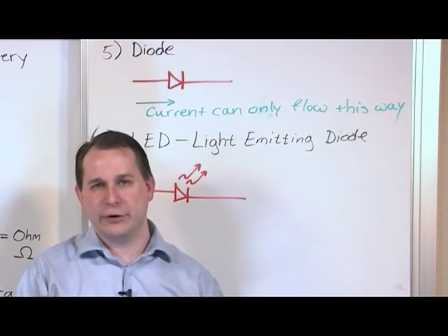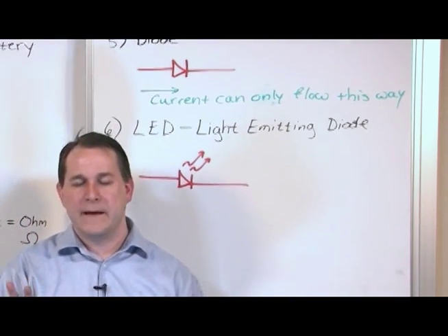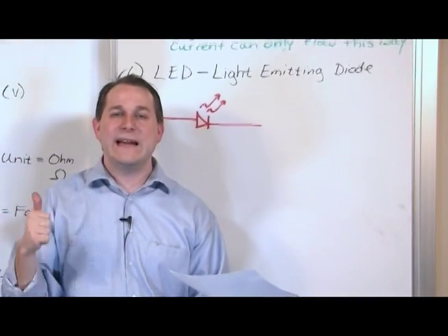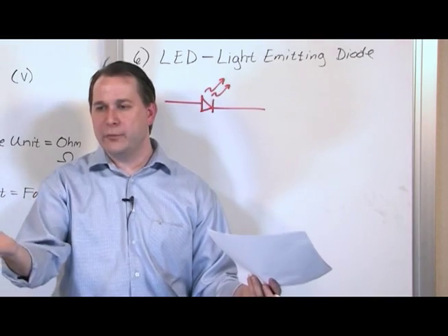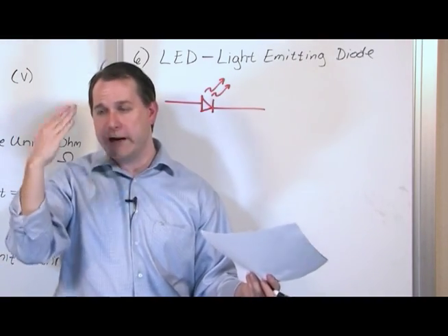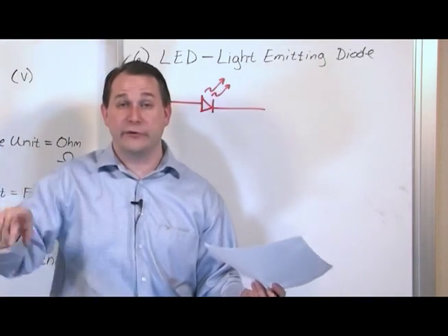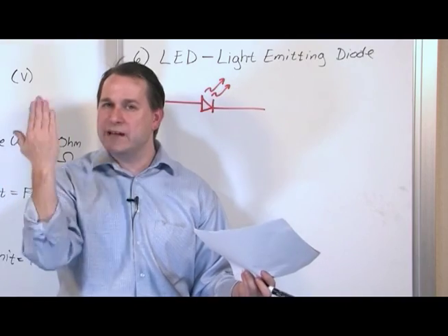What does a transistor do? Big picture. It can do two main things. The first thing it can do is it can act as sort of like an electronic switch. Normally a switch in a wall socket or something can be open, and I can open the circuit, and you can close the switch and that will let the circuit function. A transistor can also function as a switch, but there's nothing physically moving inside.